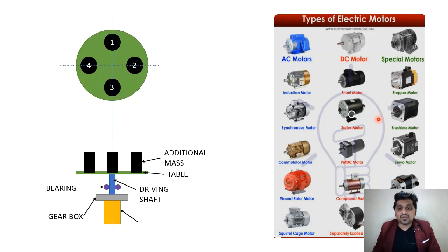So first we should study the general basic things of these motors, that is how much power, how much RPM and how much torque these motors give, and what the special motors are. Because based on our application, if we require very high accuracy, then which type of motor should be used, because there are gearing systems in the motors also, so there is backlash. So on the basis of accuracy and all other parameters we should select this motor.